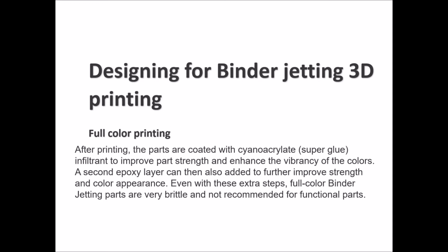Full color binder jetting parts are considered brittle parts and they are not recommended for functional parts. If you're going with full color, then usually the part is for visual purposes only and not recommended for doing any functions.